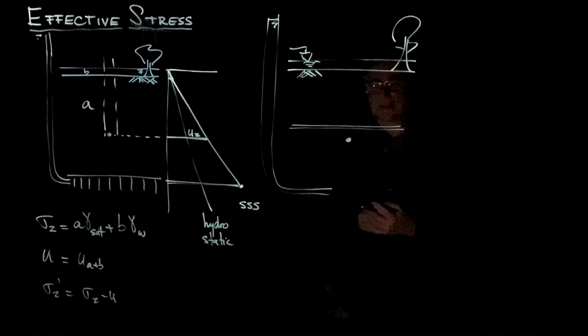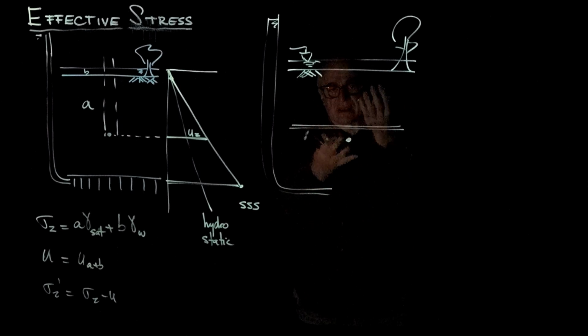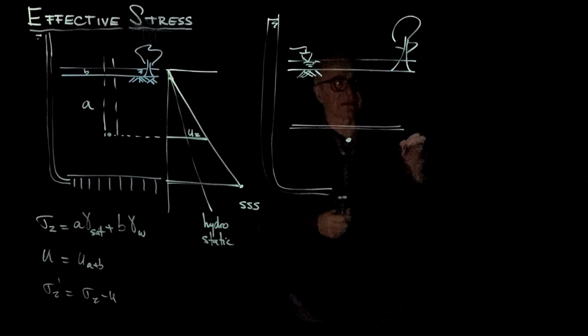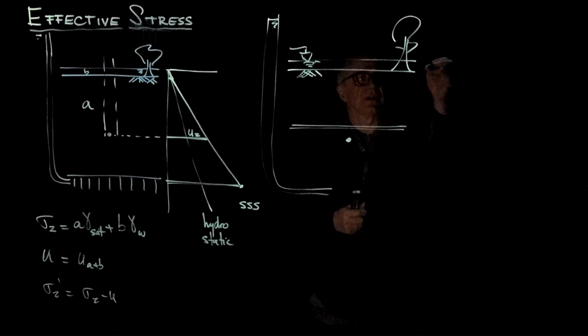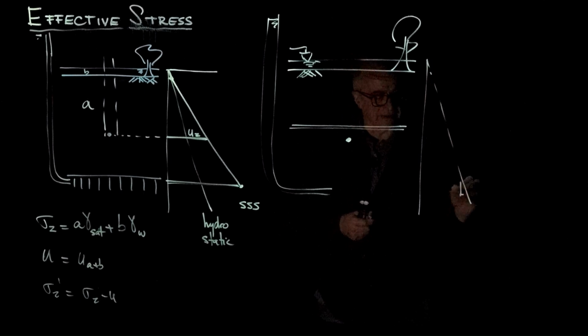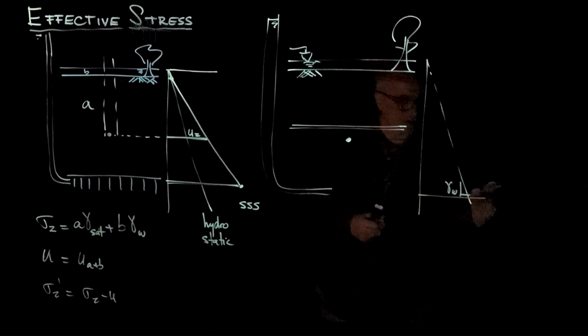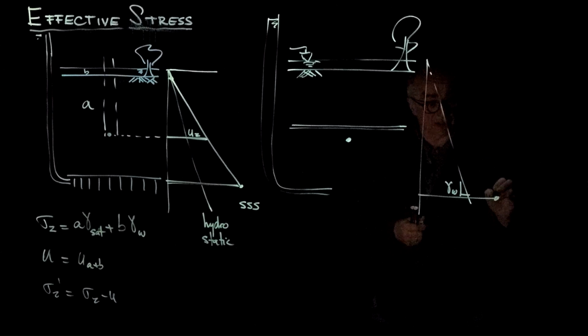So that means that there is no seepage across the system. It is hydrostatic on both sides, but from the top, the pressure is going to be increasing from this position down according to gamma water. This slope is gamma water. But from the bottom, it is going to start from the Artesian pressure, which we said is significantly higher, and go up with the slope gamma water.